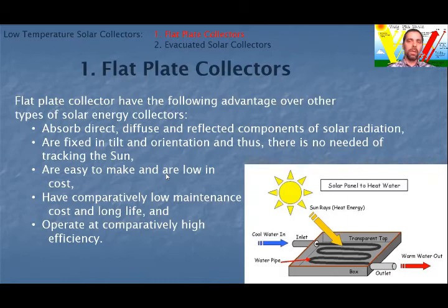It may be a combination of flat, grooved, or of other shapes as the absorbing surface with some kind of heat removal device like tubes or channels. Flat plate collectors are used to convert as much solar radiation as possible into heat at the highest attainable temperature with the lowest possible investment in material and labor.